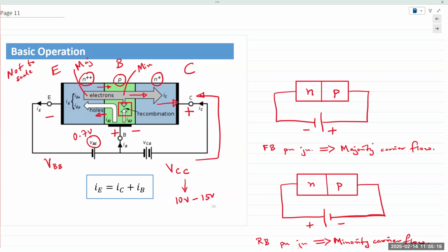We can try it in the lab, again, lab 8, that's the design of a BJT based amplifier. So in that lab, if you apply a large AC signal to your circuit, you're going to get clipping or cutoff at both ends. And you'll be able to see this in the lab itself. So again, repeating the same thing, if we are increasing or decreasing the base voltage, it's going to be very, very small.